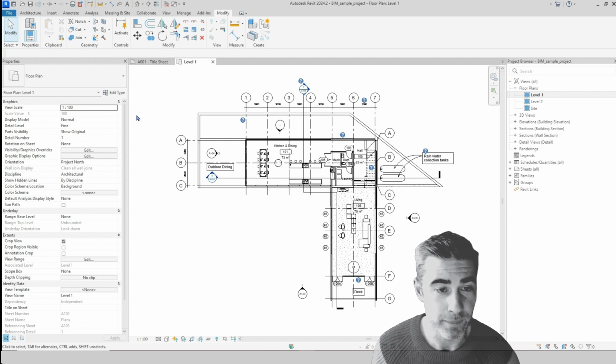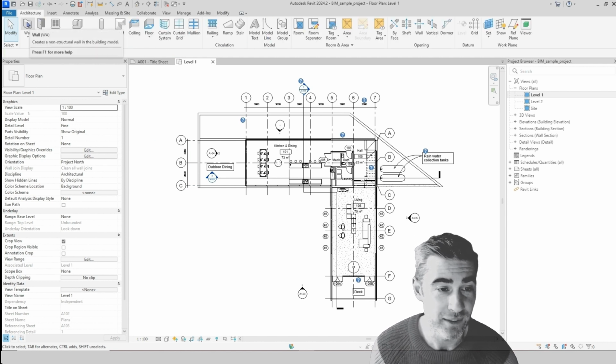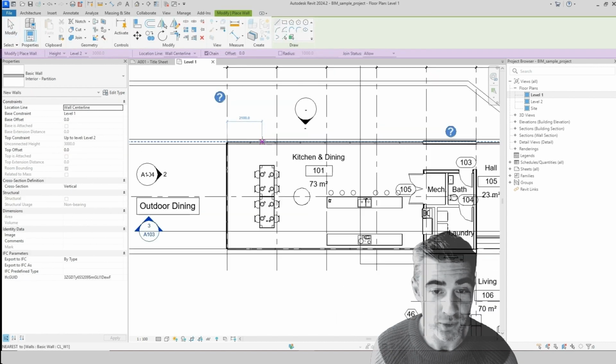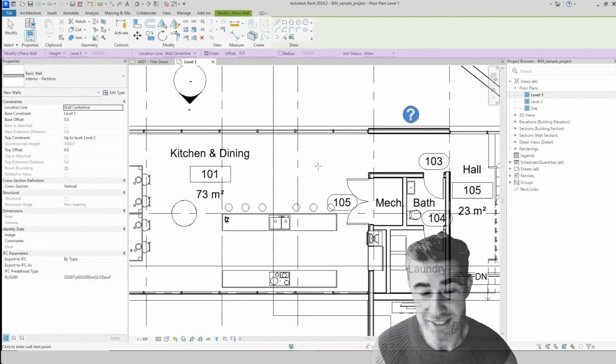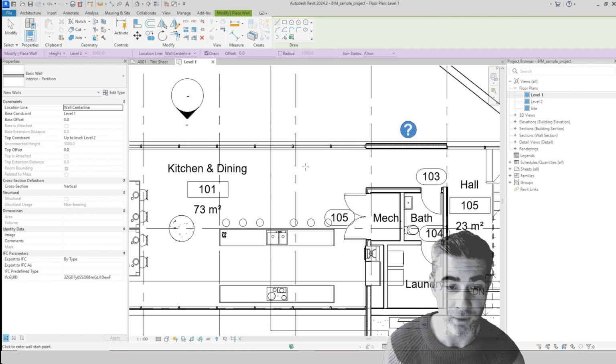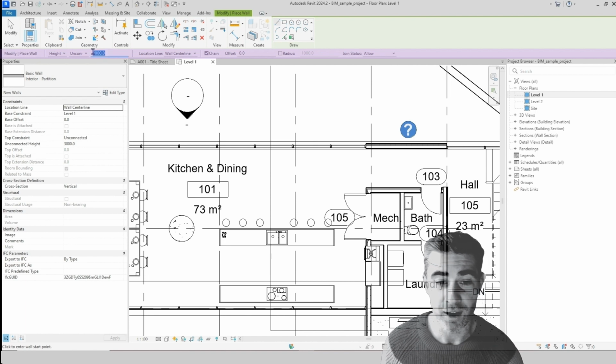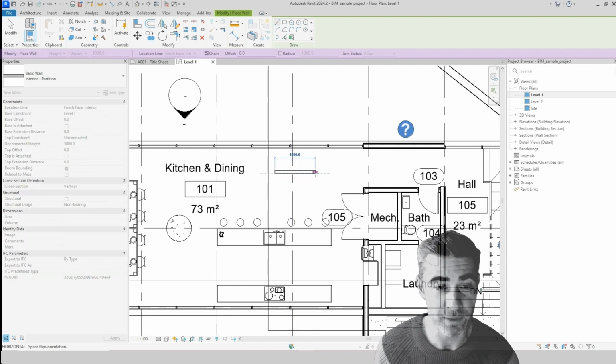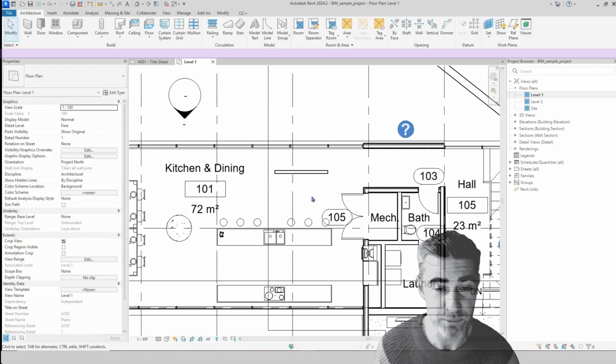Option bar, this allows us to customize new elements. This bar appears when only creating new elements or using certain commands. The content is different depending on the type of items you're adding. So for example, if I'm going to select a wall and start to draw, before I actually go to draw, an option bar will be prompted up, giving me the options of offsets or positioning of the wall. So if that's a center line, finish face, if there is an offset or height offset or drawn to a certain height, I've got those capabilities to add in those properties as I'm drawing the wall.